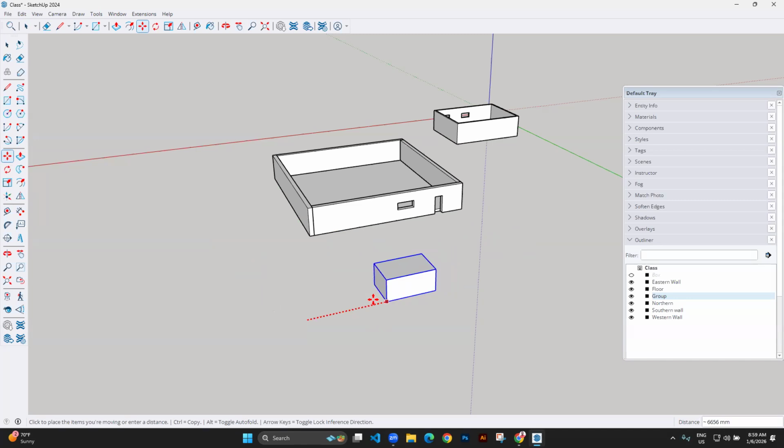The upper button, or the left or the right of the group. Yes. Then you can type in the distance. That distance will depend on where you based. So I've based on this corner, then I could say move it 5 meters away. But the 5 meters will start counting from the selected corner. Then you can type in and it will get moved.